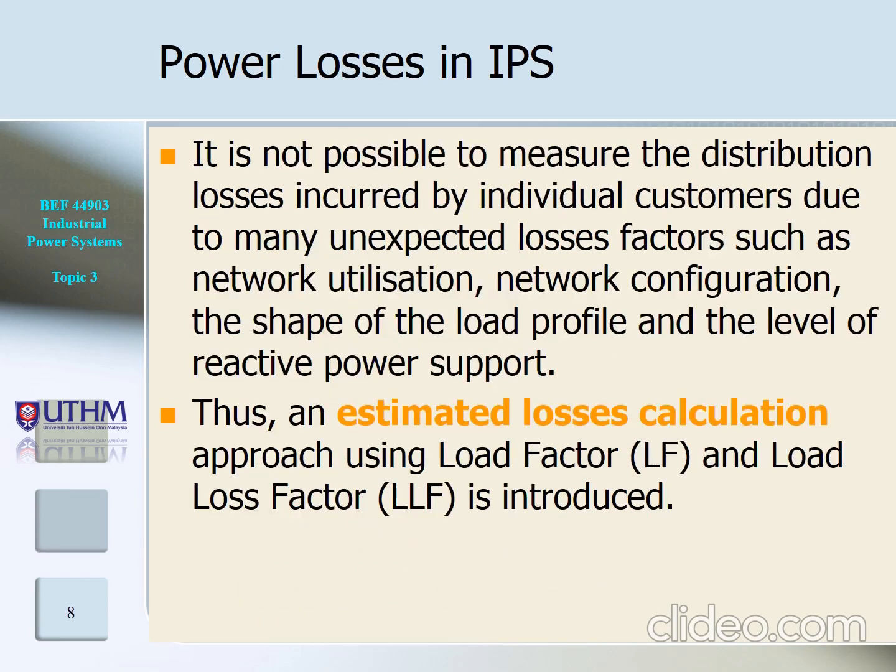Okay, it is not possible to measure the distribution losses incurred by individual customers due to many unexpected loss factors such as network utilization, network configuration, the shape of the load profile, and the level of reactive power support. Thus, an estimated loss calculation approach using load factor and load loss factor is introduced.